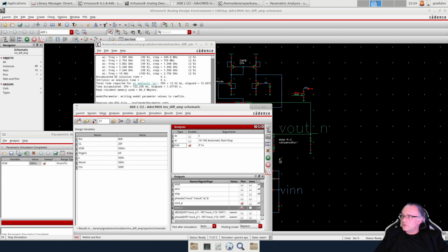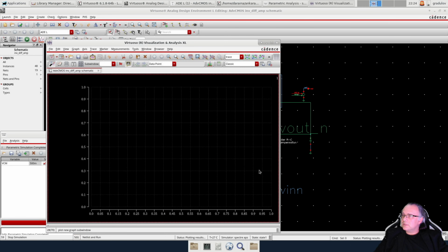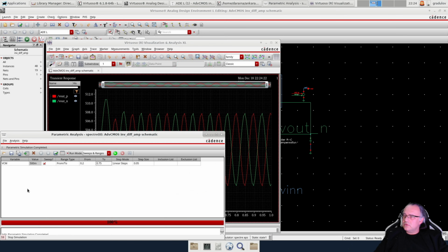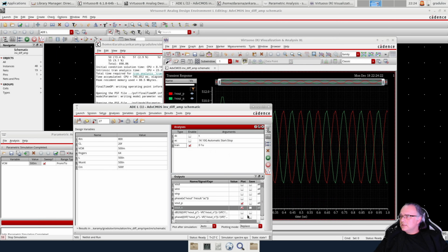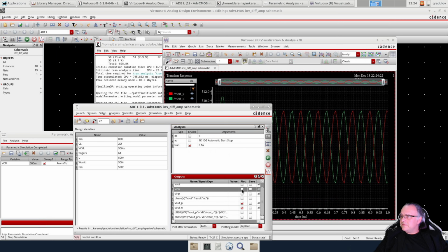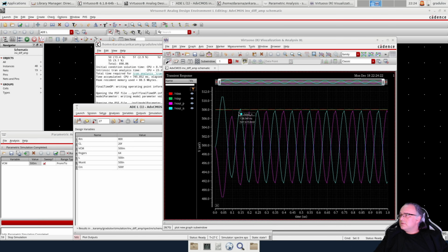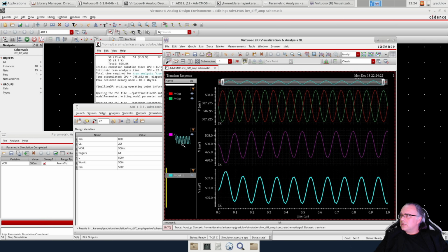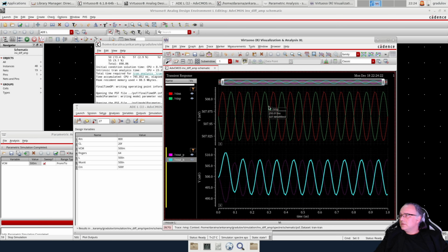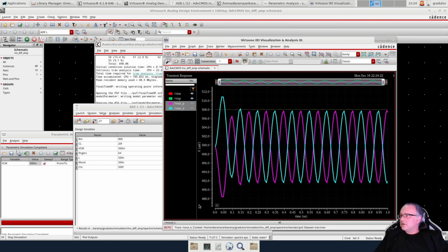So first, for the nominal 0.5 volts common mode, let's see what I get. Here it is. I'll also plot the input so that you can literally see the amplification. This is the input voltage, and then I have about 55 dB amplification. So you can see it all together.